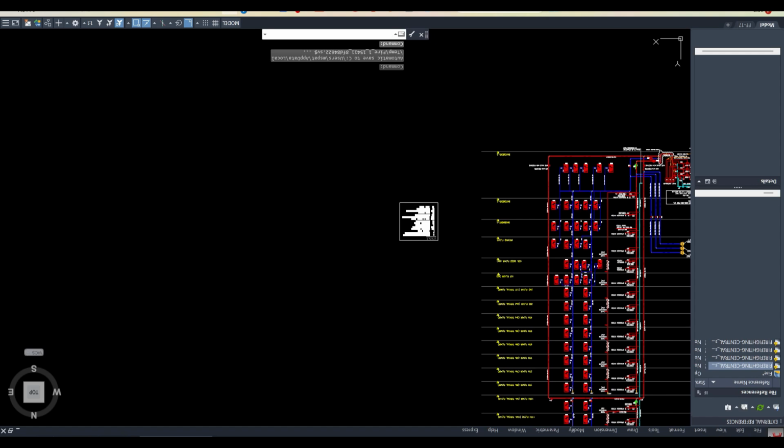So be very clear. Distance will be measured from the lowest grade till the roof floor slab. If it is less than 15 meters, it's low rise. If it is 15 or above, but not more than 23, whatever height building is in between, that is mid rise. From 23 meters to 90 meters, that is high rise, and from 90 meters and above, super high rise. Got it? Okay.